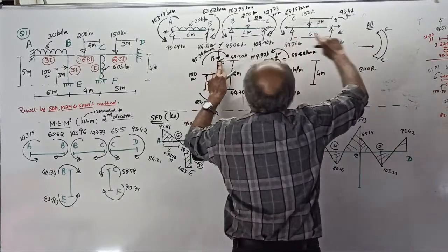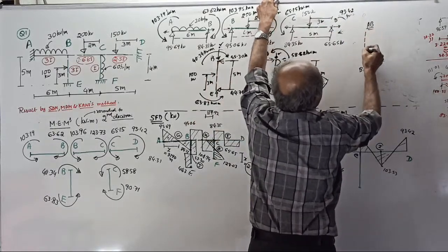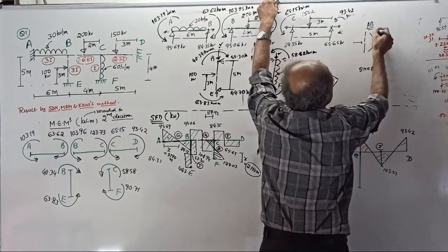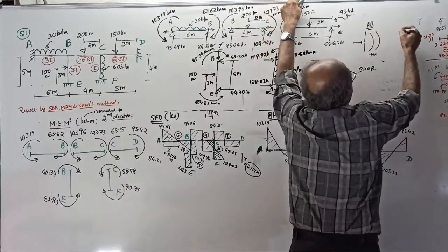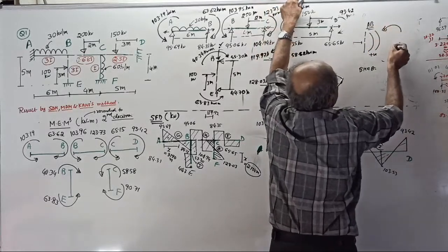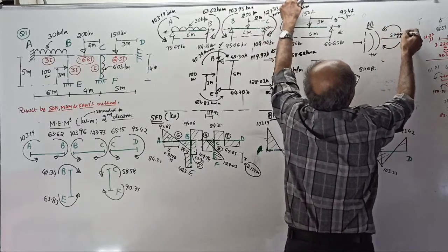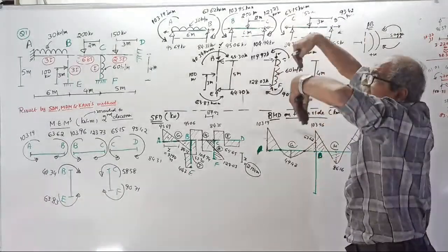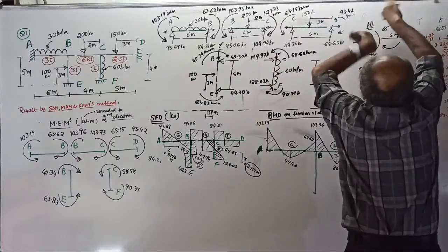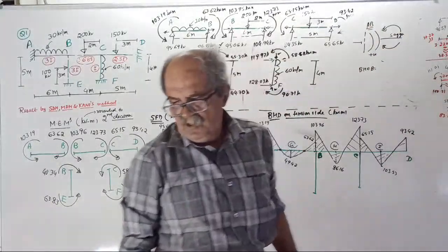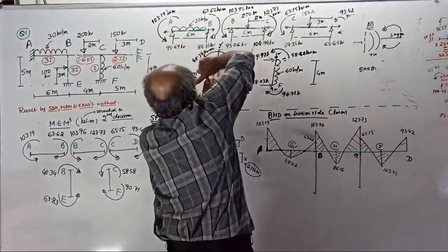Now, bending moment at B. Here. See, this is sagging. That means, or I will do one thing now. See, AB member, load is here. This I will take sagging positive. Therefore, to sag, you need this moment and this moment. This is called sagging. Agreed? If I stand here, this is called sagging. Yes or no? You stand here. See, this is called sagging. Tell yes or no. Fast. Yes.